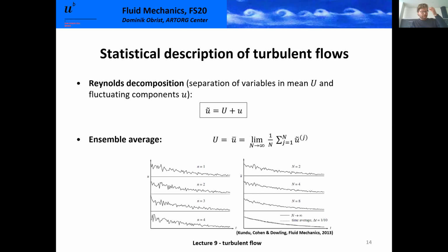So what you can do is you can actually modify the Navier-Stokes equations in a way that they're written not in the variable u tilde, the variable of the actual turbulent flow, but in function of the mean flow. So how do you do that? You take the full Navier-Stokes equations. We're not going to do this now, I'm just explaining to you.